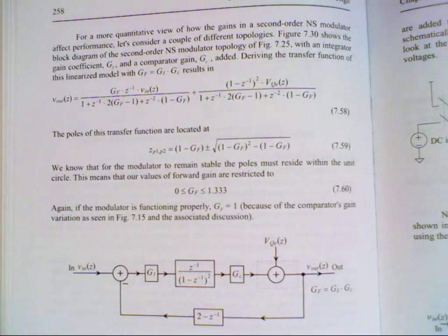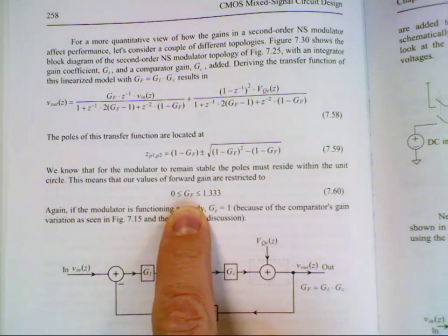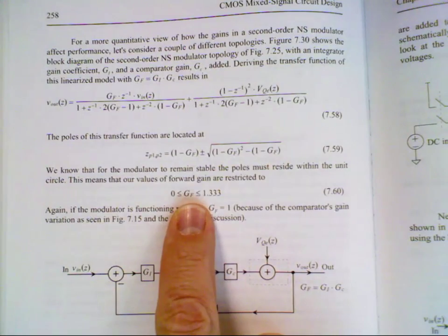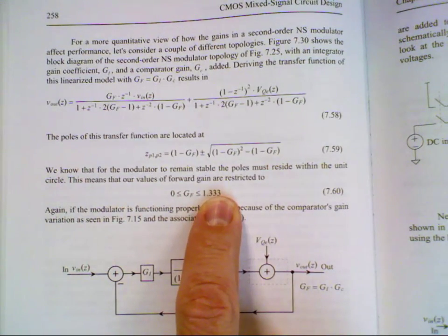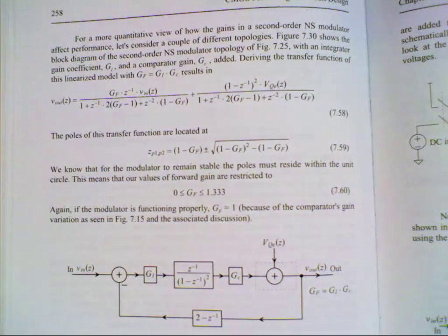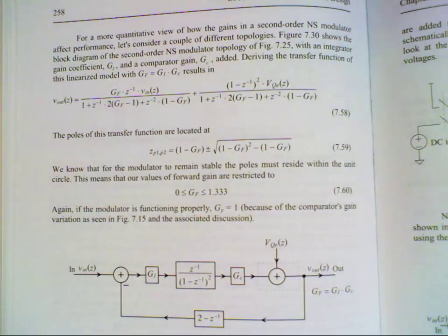So what was it for the first order modulator? Does anybody remember? What was this equivalent equation? 2. The maximum was 2, so the stability was easier for the first order modulator, and intuitively you're simply repeating, oh, well, the modulation noise is higher at high frequency, so yes, it's going to be more prone to instability.